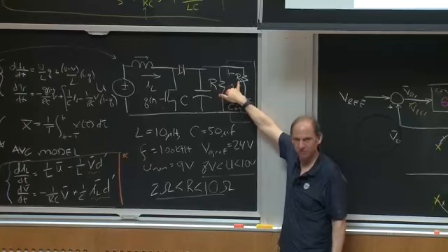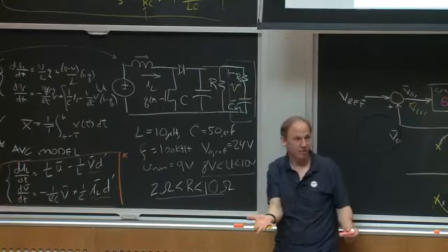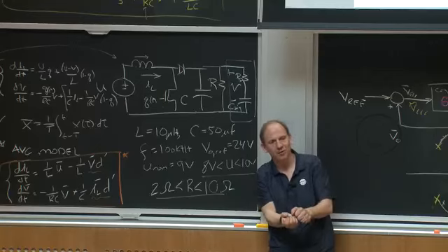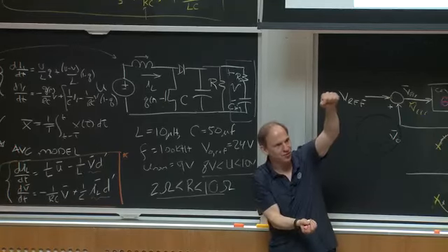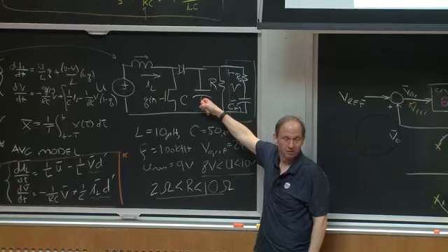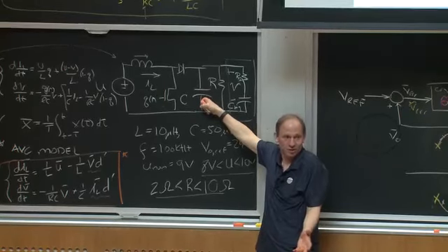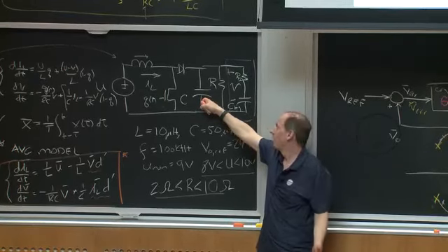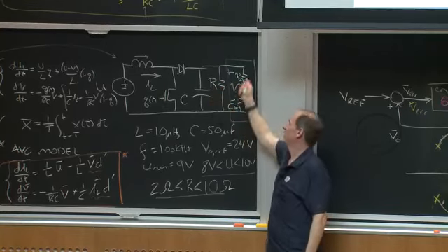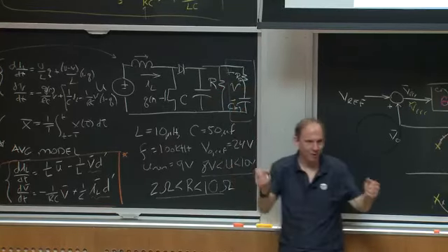It's more expensive, right? There's some things you can't change, right? I mean, some things you must change the plant. If I want to reduce that amount that voltage is going to swing up when the load steps down, I'd better go get more capacitance. There's no way around it, okay, because there's nowhere else for the energy to go unless I'm going to somehow dump it. So sometimes you have to change things, but you don't tend to like to add hardware if you can do it in control, okay?